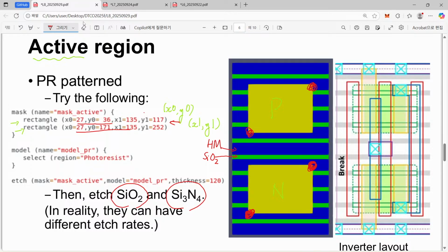Well, silicon dioxide and nitrides are attacked and damaged, but PR just remains. Usually PR is regarded as a sacrificial layer. So although PR is damaged and etched away, as long as it protects the remaining fin pattern or silicon dioxide or nitride pattern, it's okay. We don't care about the full recovery or full health of our PR layer. PR can be sacrificed quite easily.